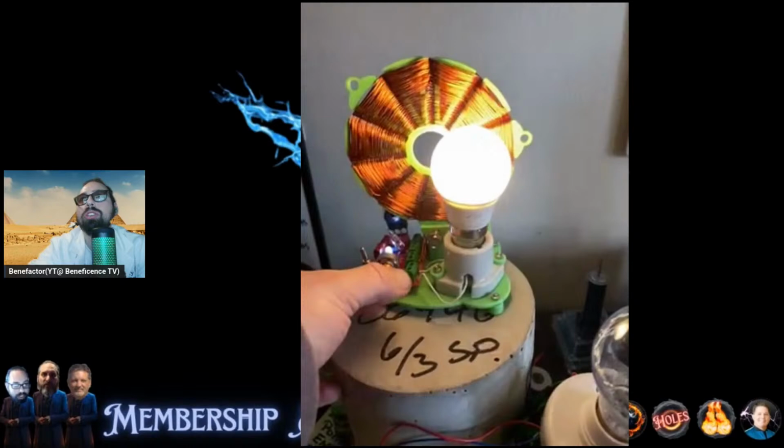So the switch actually was broken when the device was sent to me, the lumen lamp. This switch on the left-hand side, you know, these switches are kind of cheap sometimes. They are sent out from the manufacturer. Some of them are broken, quality control issues or whatever. So I have to go ahead and desolder that. But until I got the desolder braid, what I did was just solder a line on the back of the board, so it's permanently on.